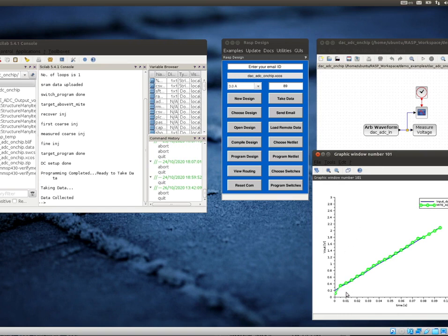This is simply doing a sweep where you can see the initial blue line is the inputs to the sweep, and the actual values that are measured out are the green dots. And you might think this is a very simple measurement, just connecting two things, a DAC and an ADC, and it is. But remember, this is a DAC connected through to an ADC type device on the chip, which is actually compiling into the chip, which then runs through the programming infrastructure onto an on-chip DAC and back into the SRAM memory through all of these data points. So in sequence, it allows you to see exactly how these tools work and the various pieces.